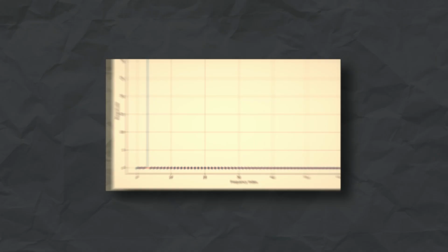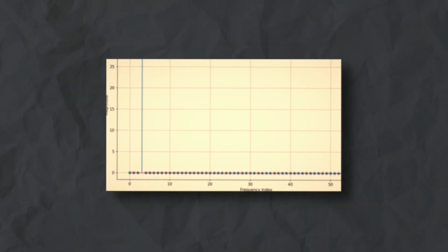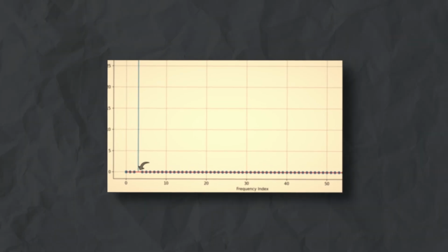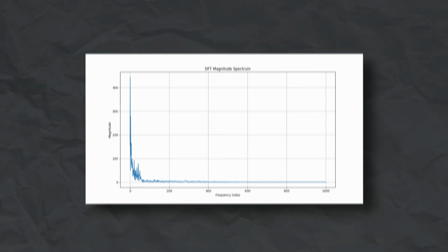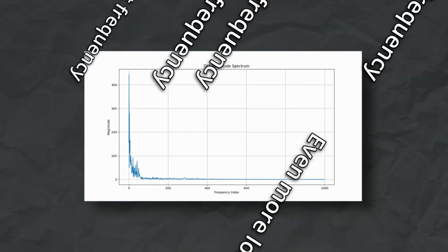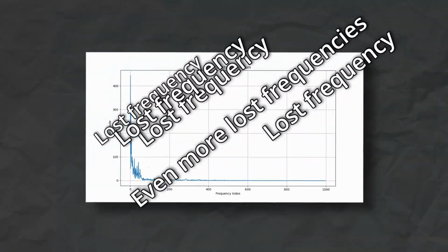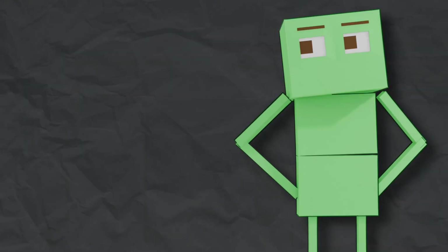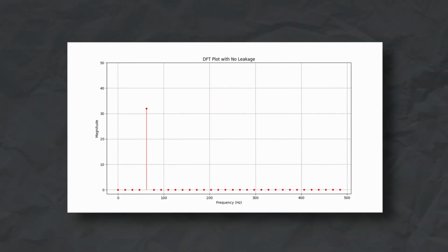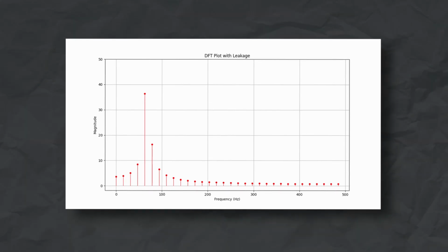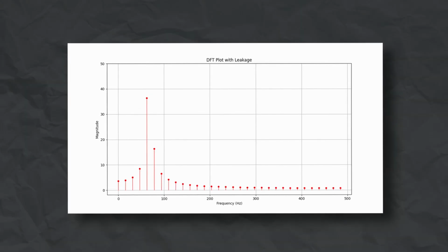Another question I left off with in the DFT video is, what would happen if we're not able to create a frequency through our discrete indexes that matches a certain frequency present in our signal, since we can only test a discrete number of frequencies? Well, those lost frequencies get spread out across our outputs for each discrete frequency value, thereby leaking into all of them. I think it's better showcased visually, so here's a DFT output where we can exactly pinpoint a frequency in the list we are testing, and here's a DFT output when we can't. The only difference is something around 4 Hz.